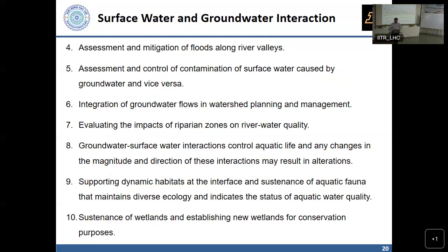I wanted to spend a few slides just quickly talking about groundwater exploration techniques: surface methods, subsurface methods, and geophysical methods. We will simply mention them. Surface methods are easy to operate and implement. You can see surface water, it's easier to access, and it requires less research work and less background information. Facilities that you require to manage surface water are going to be easier to obtain. Subsurface methods of groundwater exploration basically require a much larger investment. You have to invest in digging wells, doing borehole logs, characterizing the subsurface, and so on.